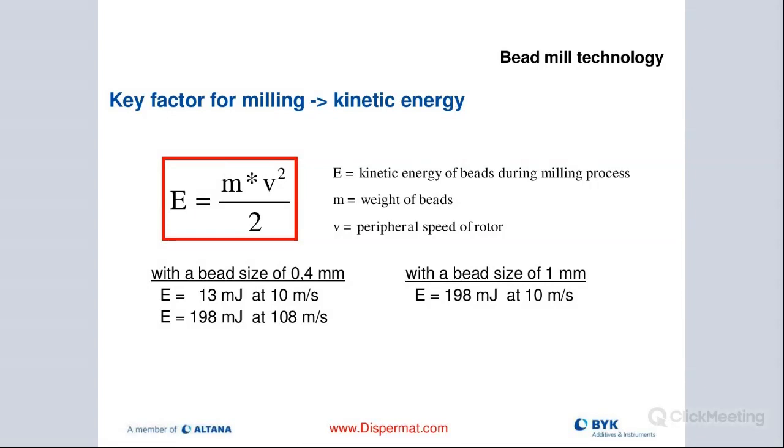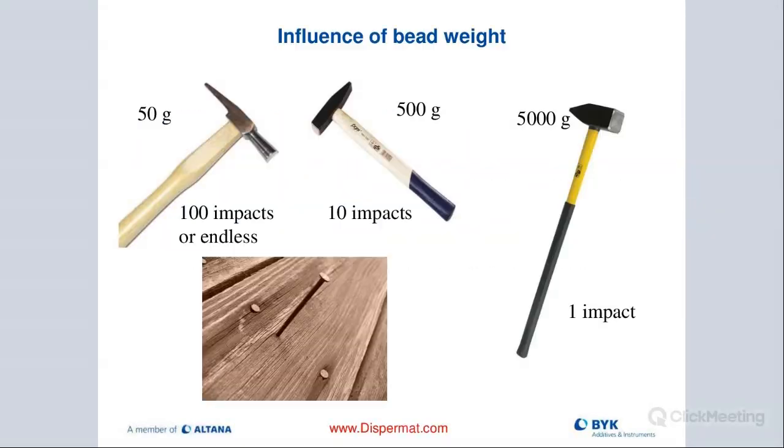And we want to stick with ceramic and not steel beads because the problem with stainless steel or metal is that because of the milling action and just the beads getting thrown around the milling chamber, it's going to wear. And that would cause the material then sometimes to shift color. So if you're trying to produce a light or a white product and you're using metal beads, then it could happen that the mill base would turn gray. And we want to avoid it. Therefore, we highly recommend that you use ceramic media.